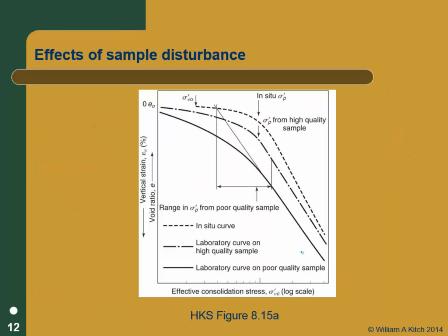So this is the one I really dislike. This is Casagrande's and Schmertmann's method for determining the field, the quote virgin field curve from bad lab data. That's my interpretation. This is the sample disturbance one. I'm sorry, this is showing you what the field curve really would look like if somebody knew, and then this is a sample that's a good sample, and then this sample is a really bad sample. And notice that, let's just do Casagrande's construction real quick on these. So on this one, I think the point of maximum curvature is here.